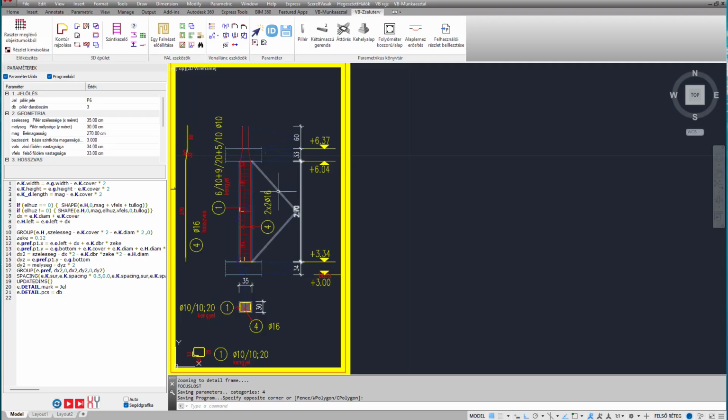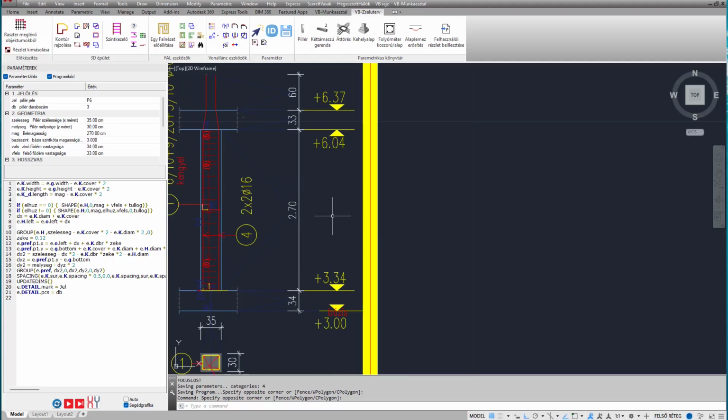The important point is that constraints can also be assigned to individual objects. For example, a dimension line can be constrained so that its 2 points always belong to a given segment of a contour object. Another possible constraint is that the y-coordinate of a level marker always matches the y-coordinate of a certain point on a contour object.